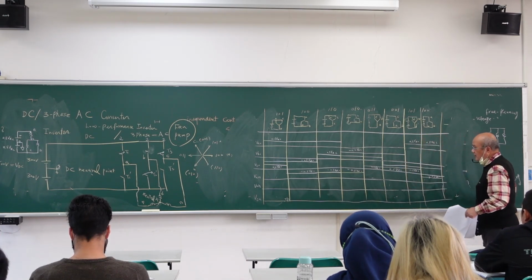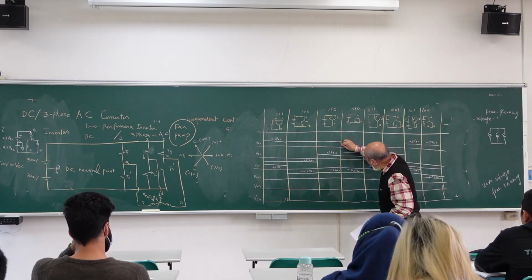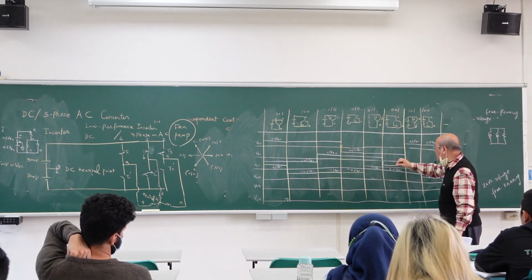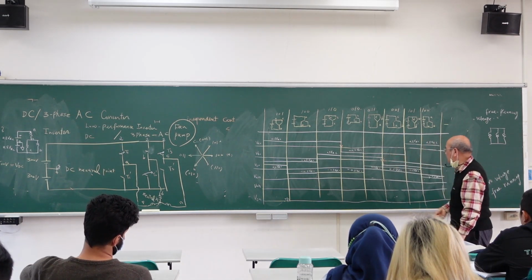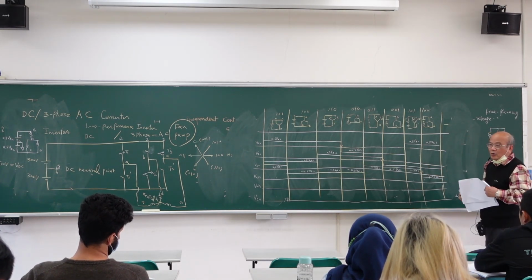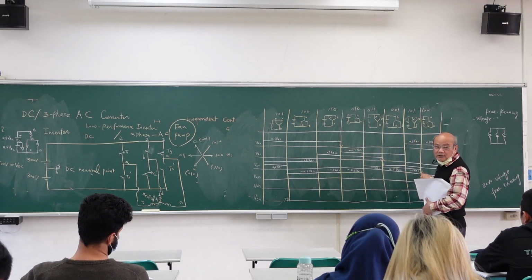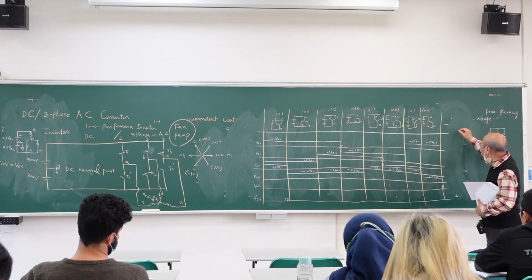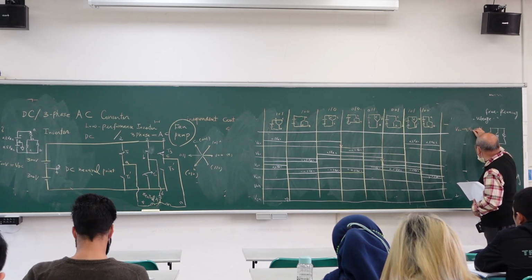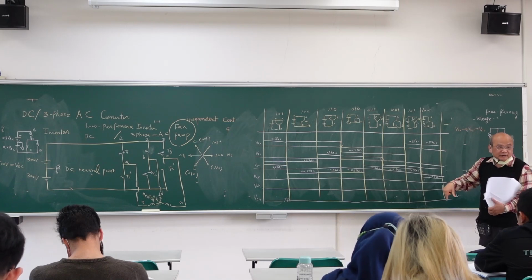So now we want to check phase sequence. VA jumps to negative here, right? VB jumps to negative here. VC jumps to negative here. So what is the phase sequence? A, B, C, right? So we have VA, VB, VC. Is it correct? Yes. A, B, C, right?